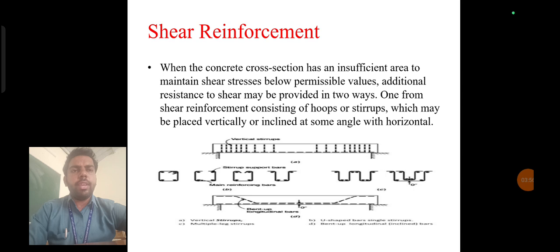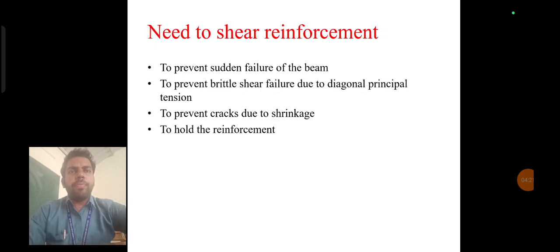See here, the figure shows that as we go toward the middle of the beam, the spacing of the stirrups is somewhat greater compared to the edges. Here, a number of stirrups should be provided on the beam. The strength of that section will be greatly improved.